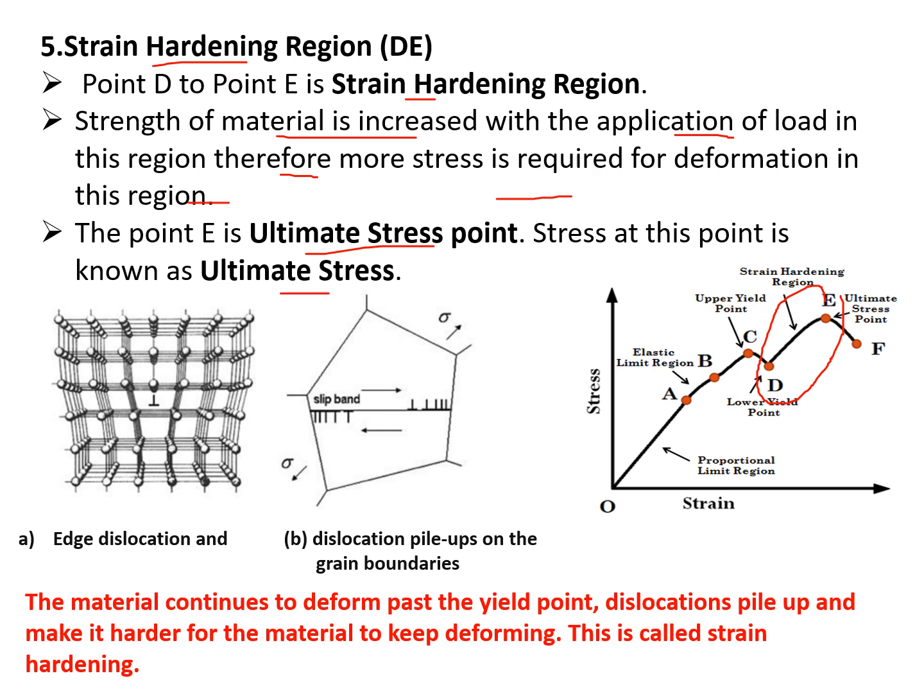Okay, so again we have to see this particular atomic theory. So this is the edge dislocation you see here. But now we are getting the different slip planes and the different edge dislocations in that material, and these dislocations move, and finally all the dislocations will be piled up in some region. So this is the dislocation, and here these dislocations are piled up on the grain boundaries.